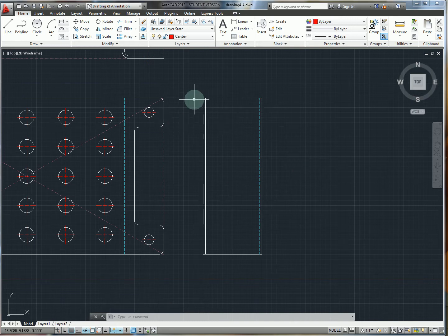So finally, at this point, we're ready to draw the center lines. And it's basically the same procedure as before. So we're going to draw, let's see, from here, the opposite side. Same way. So we're going to, again, use that same strategy. Center lines, we're going to use object snap, polar tracking, extend this, and then just kind of lazily draw a center line through.